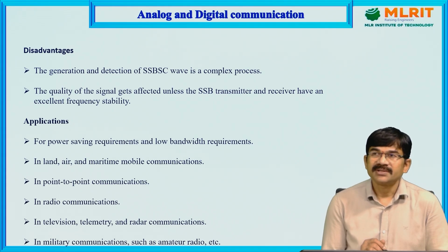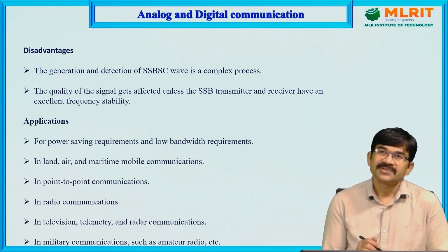Here we use the coherent detector, so we have to maintain frequency stability. The signal generated at the transmitter side and the signal generated at the local oscillator should be stable, in phase and at the same frequency.